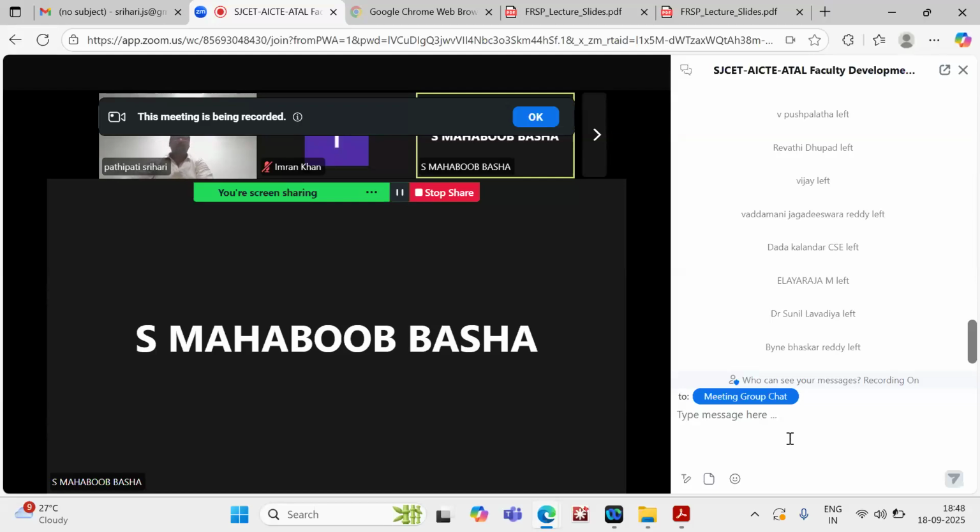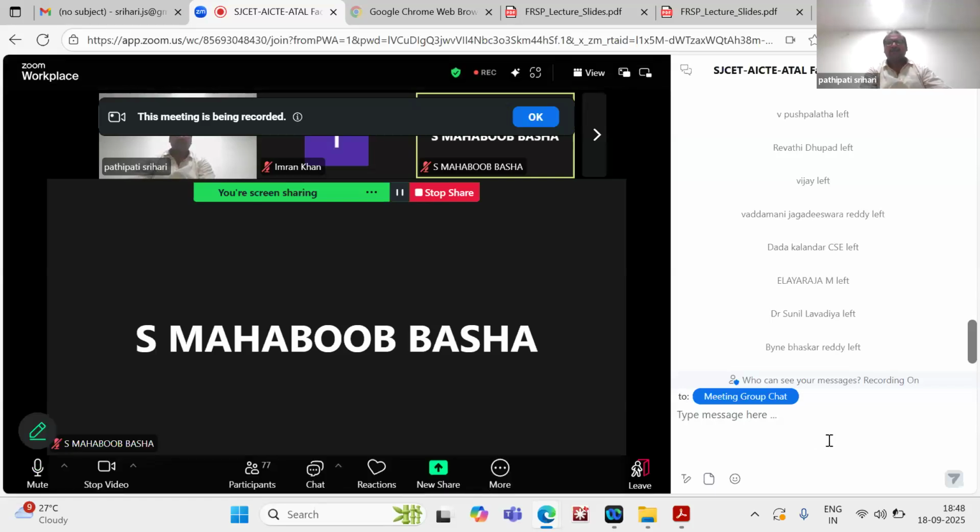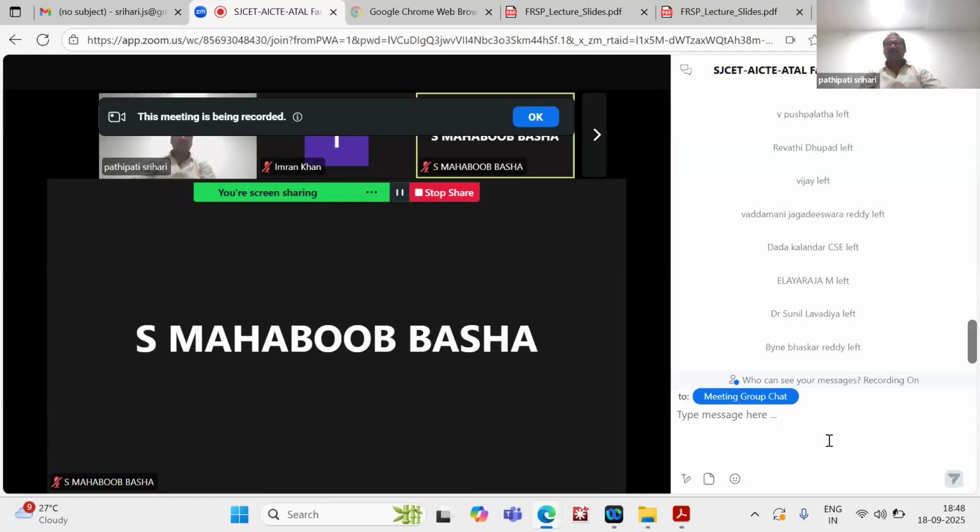That is, when you go into Y(e^jω) = H(e^jω) X(e^jω), you will get the magnitude square of X(e^jω) times the exponential of that delay term. So the magnitude square of that incoming signal is the input signal power, or energy, that you can consider. Energy in time, energy in frequency, Parseval's energy theorem: you equate and get the E, and whatever power spectral density you get in the denominator is N0 by 2. So it comes out like 2E by N0.